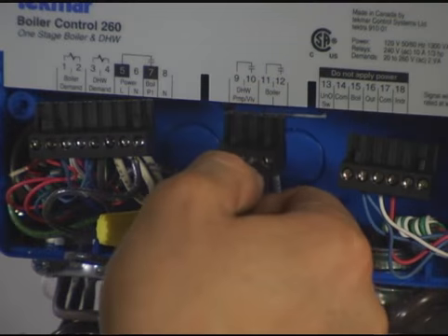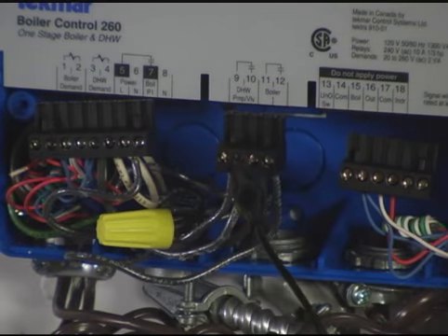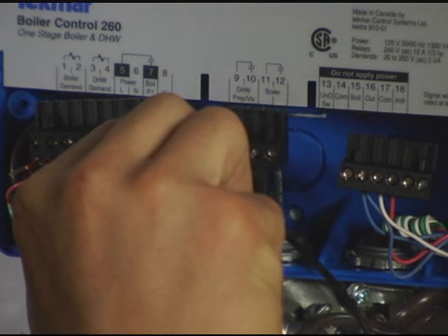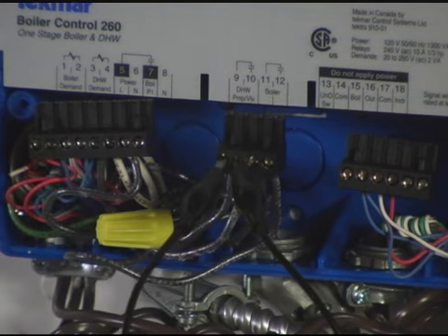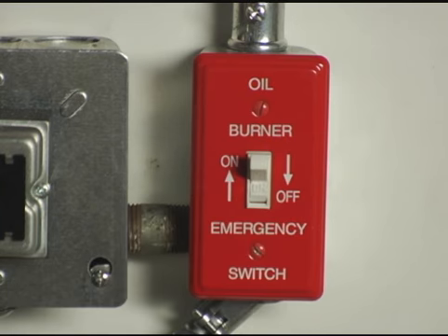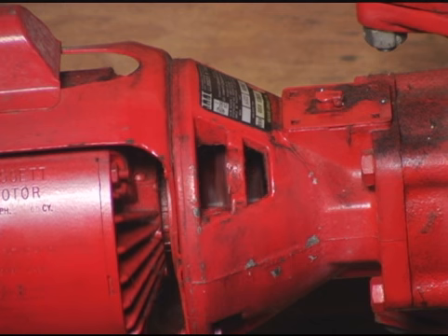If a domestic hot water pump or DHW valve is connected to the DHW pump valve terminals, make sure power to the pump or valve circuit is off and install a jumper between those terminals. When the DHW circuit is powered up, the DHW pump should operate, or the DHW valve should open completely.